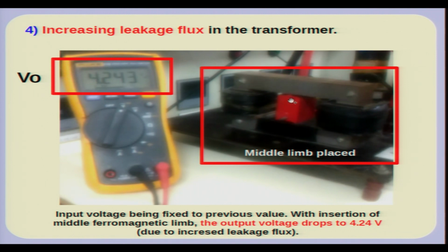Of course, this is not perfectly fitting in here, there is a small air gap here. So, the flux still preferentially flows through this path and not much flows through this, but it is still significant enough to see a perceptible difference in the voltage which is induced in the secondary coil. This illustrates that if you give a leakage path where the effective permeability is much higher, you may actually have more leakage flux and therefore your voltage induced on the secondary will reduce.